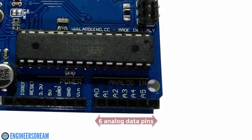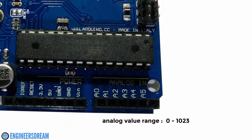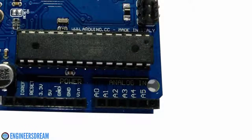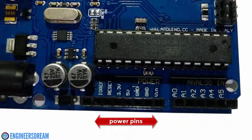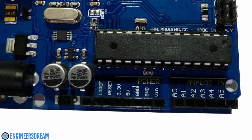An Arduino consists of 6 analog pins which are labeled from A0 to A5, and we can use these pins for connecting analog sensors or analog devices. The analog values that we can read using the analog pins are in the range of 0 to 1023. Neighboring to the analog pins, we have the power pins. Using the power pins, we can supply power to the sensors and other electronic components that run at 3.3 volts and 5 volts. As you can see, there is one 3.3 volt pin and one 5 volt pin for supply.